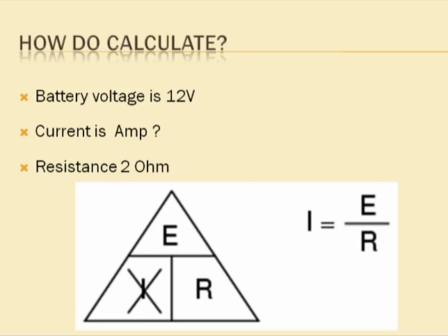If the temperature is changed, then, as in previous lectures when you studied the circuit elements, you found that the resistance R is a temperature dependent quantity. What it means is, if your temperature is going to change, then the circuit resistance is also going to change. If you recall, R_T is equal to R_0 (1 + alpha_0 T).